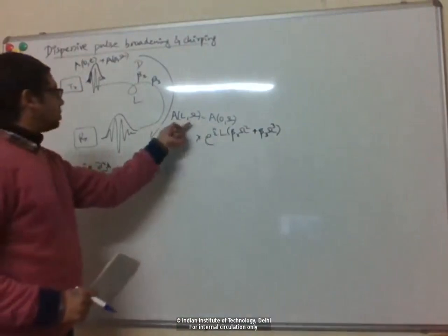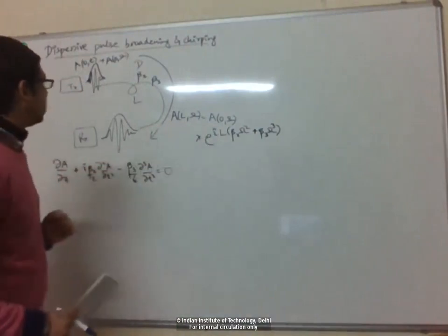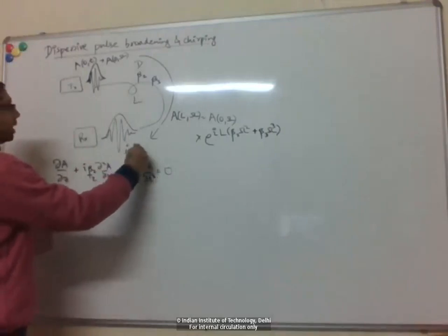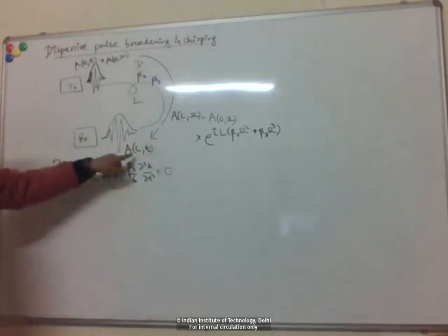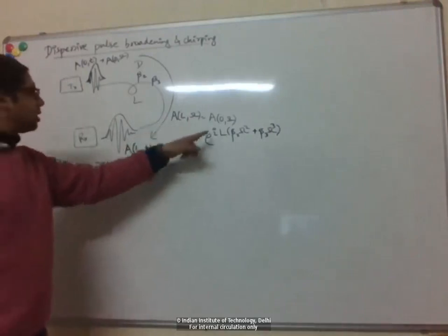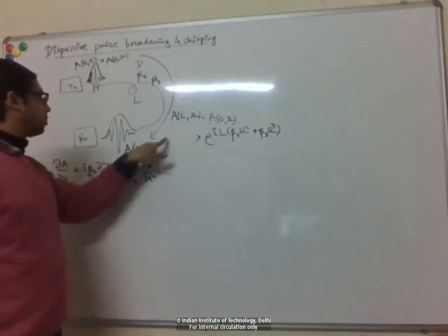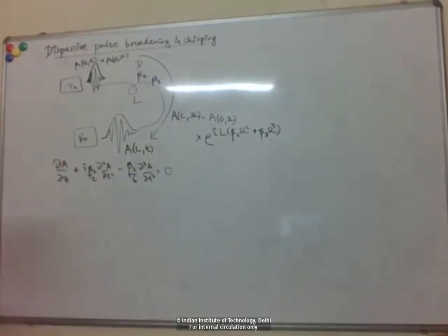So then we now know the spectrum here at the receiver, and then to calculate what the pulse looks like here at the receiver in the time domain, we just take the inverse Fourier transform to go from the frequency domain back to the time domain.